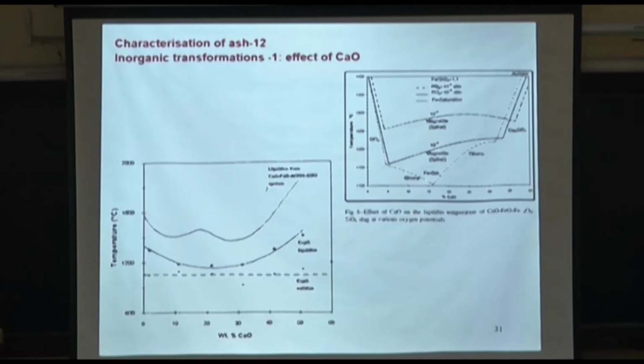Only if it is crystalline through X-ray diffraction. Otherwise not. So the best thing is to do the EDX, get the semi-quantitative elemental composition, and it doesn't matter if it's amorphous or crystalline. Take a complementary measurement with X-ray diffraction, check that yes, it matches, so I am on the right track, put it onto the phase diagram, and find out.